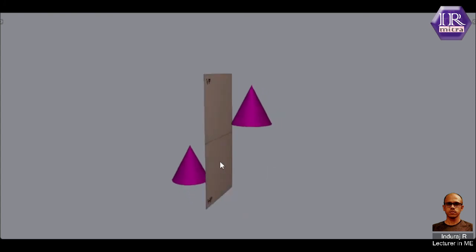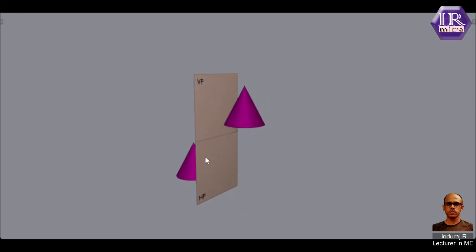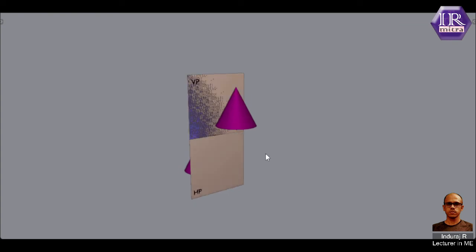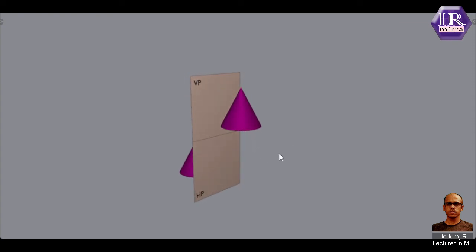After getting this, we will copy these views as such into the 2D drawing sheet. So we will be getting two views, that is the front view and the top view. So minimum there will be two views for the multi-view projection for an object in the first quadrant or in the third quadrant. Now we can discuss the point that I made previously, that usually for a 3D object we are not making any projection in the second quadrant or in the fourth quadrant.